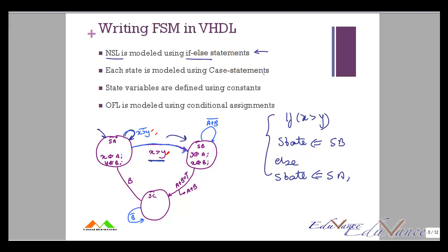Now each state can be modeled using a case statement. If you remember, I can say case state is when SA, which is when I am in state A, I will say X is A, Y is B. So this is your case statement.